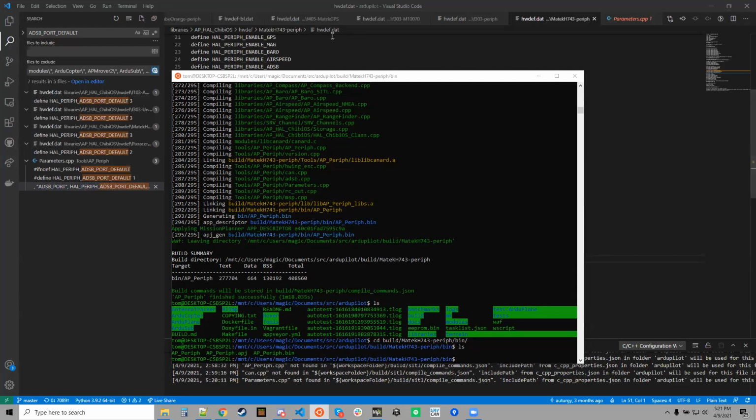Yeah. I've actually been thinking there's a couple of ways we could do this. One is subdirectories on the SD card, where the subdirectory is named after the string node name, and you could have a firmware in there, and we could support a bootloader client inside ArduPilot. So that's one approach. Another would be a tmpfs.